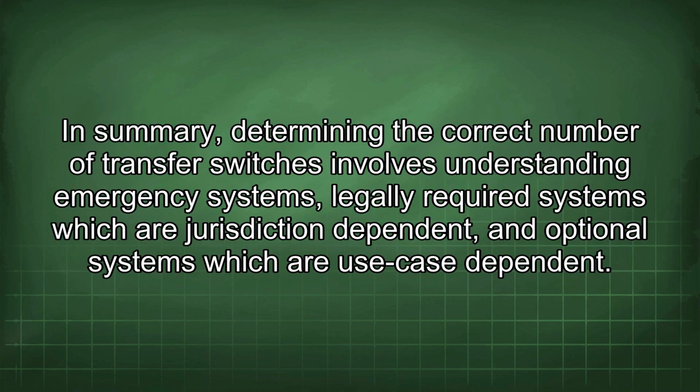In summary, determining the correct number of transfer switches involves understanding emergency systems, legally required systems which are jurisdiction dependent, and optional systems which are use case dependent.